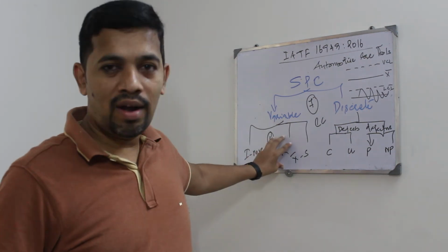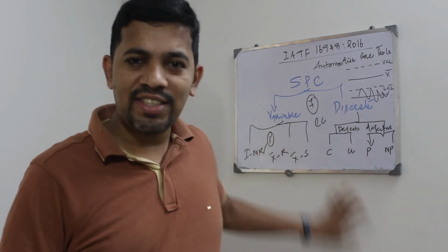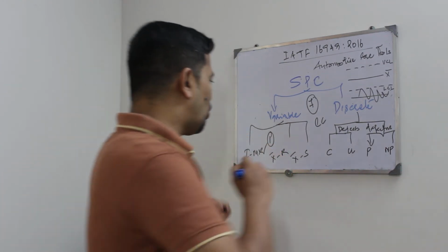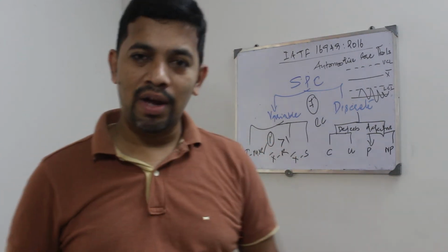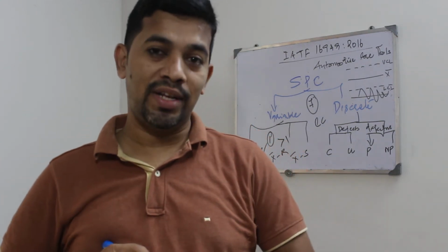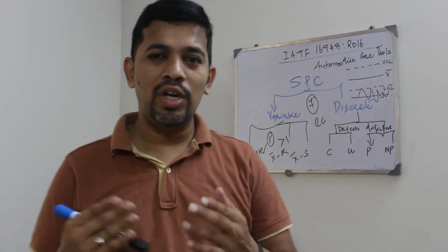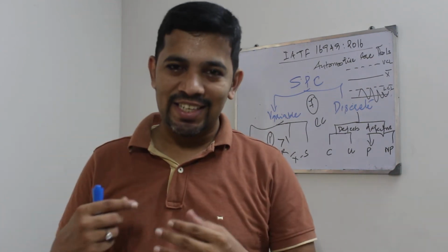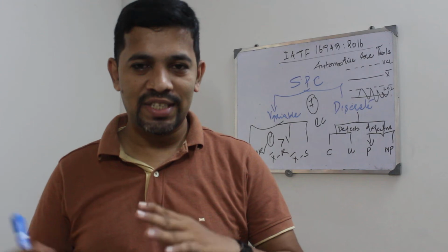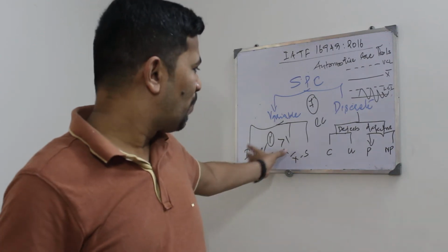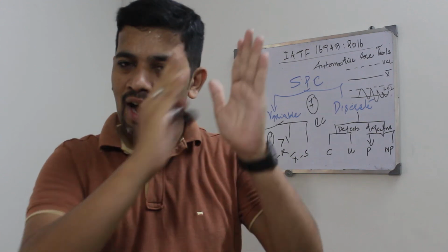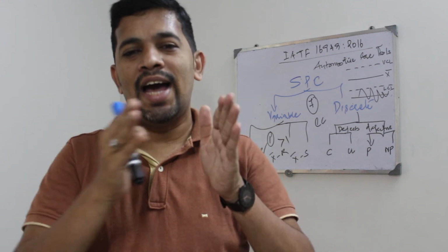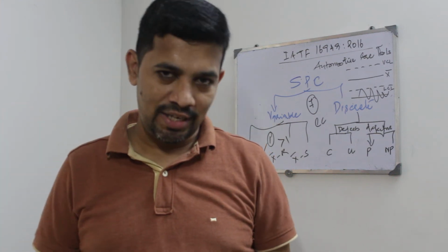So that is called the X bar R chart. The X bar S chart is not widely used. Even if you have multiple things, more than one, you can definitely use the X bar R chart itself. You don't need to use the X bar S chart. Why? Simply, range is easy to interpret. For example, maximum minus minimum is range, whereas the X bar S chart is a difficult one. Why difficult? Standard deviation is difficult to interpret. So therefore, in variable there are 3 charts: IMR chart, X bar R chart, X bar S chart, but predominantly the IMR chart and X bar chart are used.